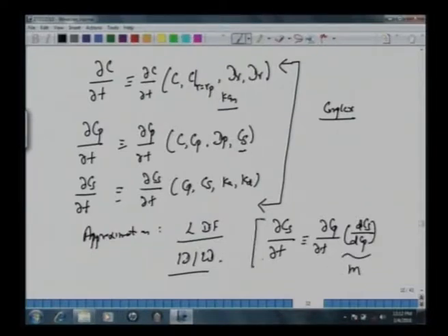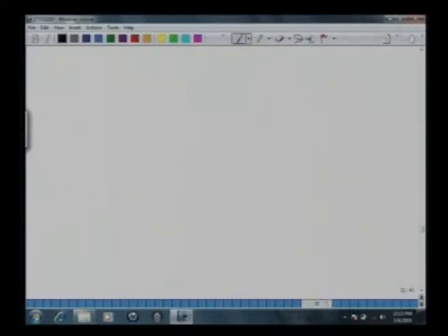So one very common example is that we assume that all rates are quite fast. Everything is controlled at the end by the rate of adsorption and desorption. So there are similar and different ways of approximations. We said that for this course we will make only very simple calculations. The one very common simplified calculation here is the concept of this MTZ.